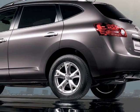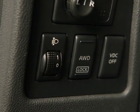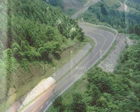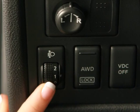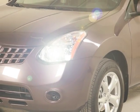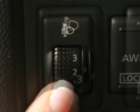When driving on a flat road without a heavy load, the controls should be set at 0. If the roads become hilly or your load becomes heavier, you may want to lower the headlight axis. Simply adjust the switch to a higher number until the headlights are at the desired level. The axis of the headlights will lower as the numbers on the switch get larger.